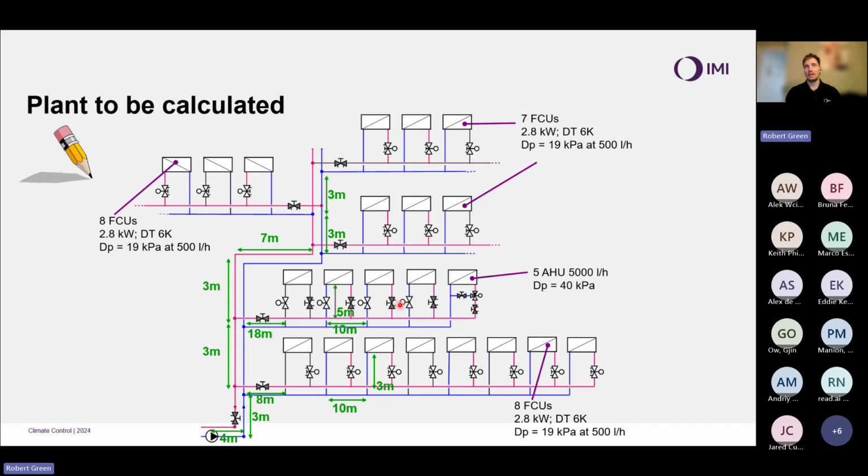Relatively speaking, if you think of it from a drawing perspective, this is like a hybrid between a schematic type drawing and a layout. Getting the layout drawing to have the pipework lengths, and the schematic type drawing to show me a nice, easy, simplified layout there. And to size that, how do we size the balancing valves? How do we size the balancing control valves? How do we size the pump? How do we size the control valves? All of this sort of information.